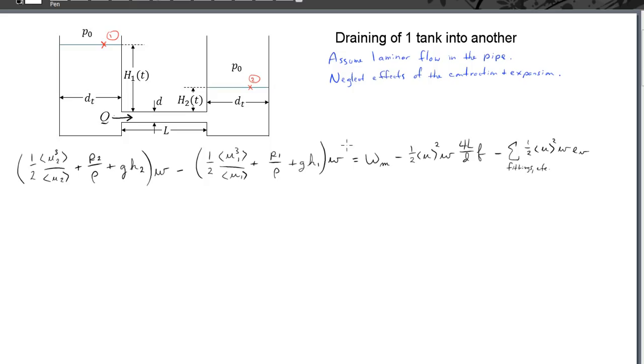So the main thing is the mechanical energy equation in the quasi-steady approximation provides an expression for the velocity as a function of other parameters in the system, such as the height difference, gravity, etc., work being done in the system if there is something like that. And once we have an expression for the velocity from the mechanical energy equation, we substitute into the unsteady form of the mass balance, and that allows us to obtain a differential equation for the change in the height of the liquid level in each of the tanks.